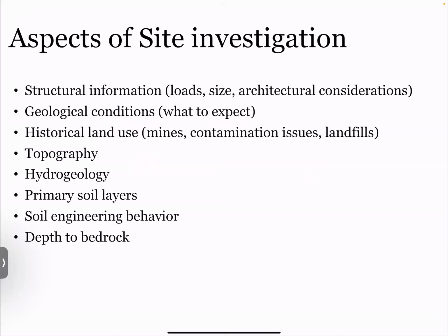So some different aspects of a site investigation, or sometimes called due diligence in some disciplines. Obviously, we want to know the structural information. So what are the loads being applied at our site? The geologic conditions, so the geologic maps, the history of the area, the topography, hydrogeology, the general or primary soil layers, and then some of the anticipated engineering behavior and the depth of the bedrock.